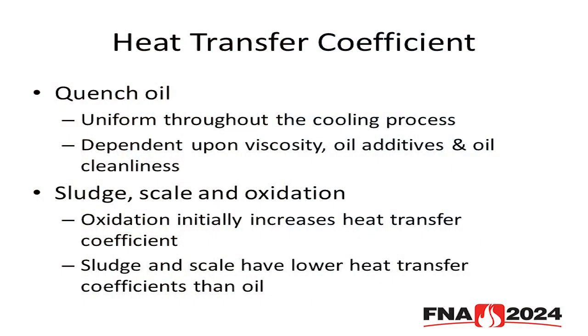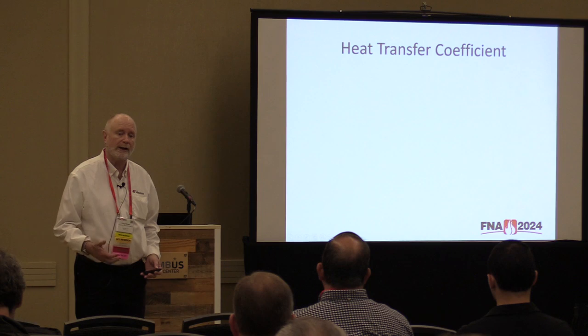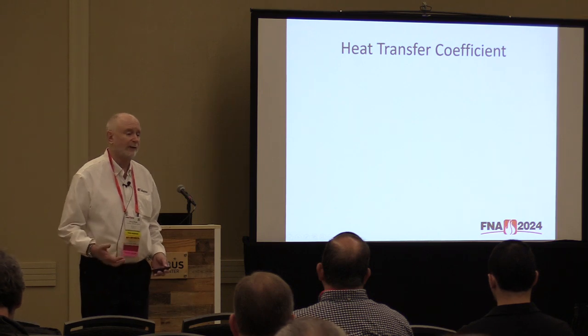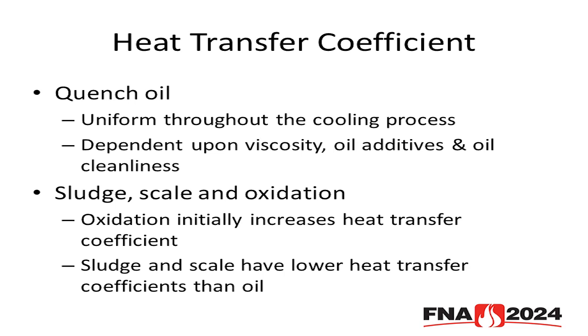Heat transfer coefficient, that's something that we always monitor and look for when we're evaluating a quench oil. It's how quickly the oil or any other material dissipates heat. For a quench oil, it's uniform through the cooling process. It's determined by the viscosity of the oil, the additives, and the cleanliness of the oil.